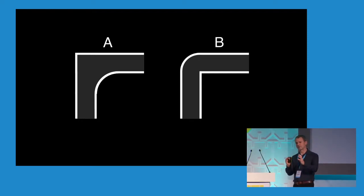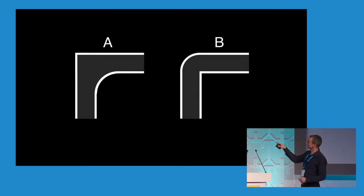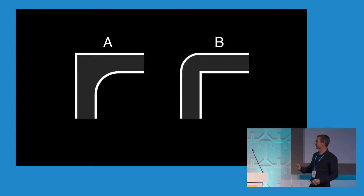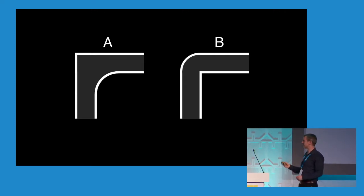So as it's moving through different geometries, you want to try and keep that cross-sectional area consistent. And actually, if you consider a ball rolling through A and B, the ball will roll through B exactly as it runs around the corner, whereas A is getting larger and smaller again. The other interesting point to note is that for anybody that's done any plumbing at home, you'll probably recognize that the vast majority of plumbing joints look like B, not A.